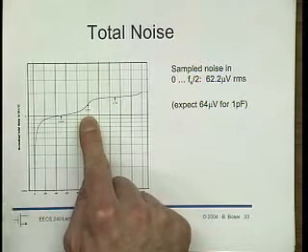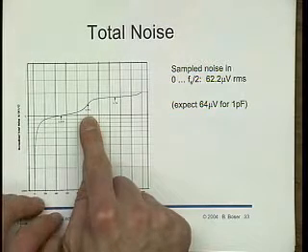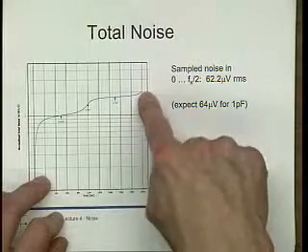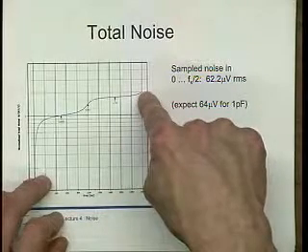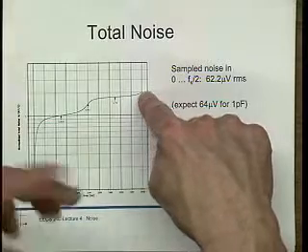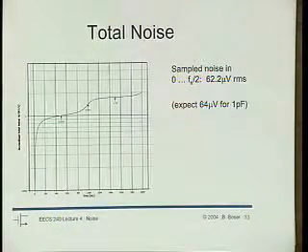Maybe you have other ways, but a circuit designer's approach is pretty interesting. And then up here, we have quadrupled the noise bandwidth, and lo and behold, the noise now is also square root of 4, 2 times bigger. So apparently, this SPICE simulation actually does work. It gives the right result.